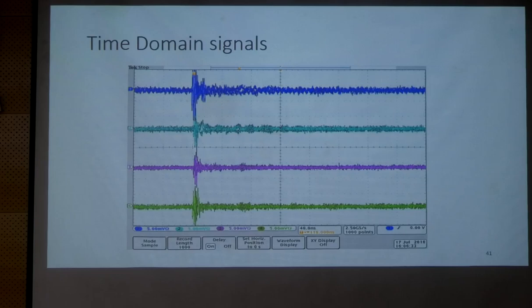Even nowadays, other types of sensors, fiber Bragg grating sensors, are also being used. The particular wavelength shows, for example, the temperature of the coils, everything we want to know. If it crosses a particular temperature, it shows a higher wavelength. In that way you can detect it. But the sensor has to be inserted in between the coil.